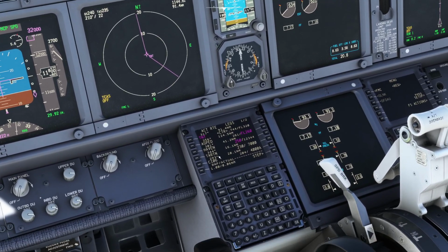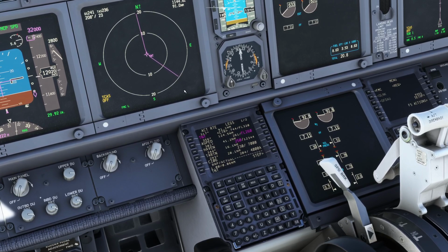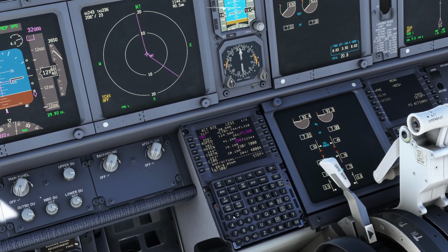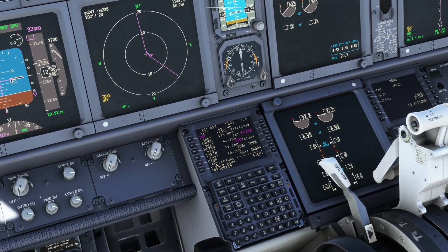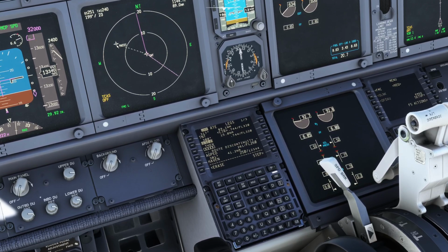So what we can do is key into the FMC TNT, and then a bearing from TNT, so 300 degrees, then a slash, and then the distance to go, so 15 miles after TNT at 300 degrees. So to insert a waypoint, remember we can just select an existing one, and it will insert it in front of it and move that down. Okay, so that's done that. Look what's happened. So 300 degrees from TNT, 15 miles, and it's made a new waypoint called TNT01.